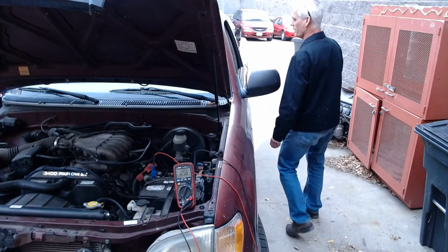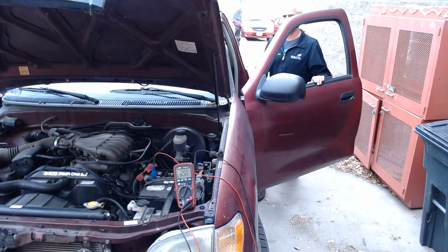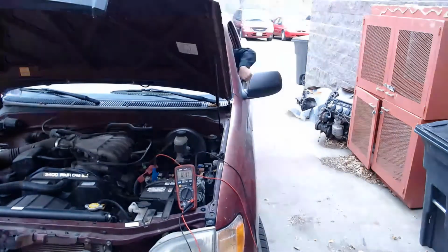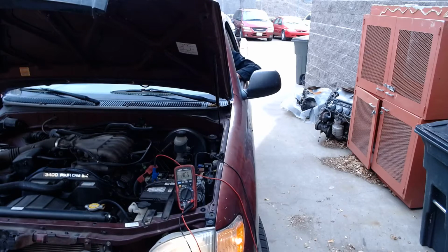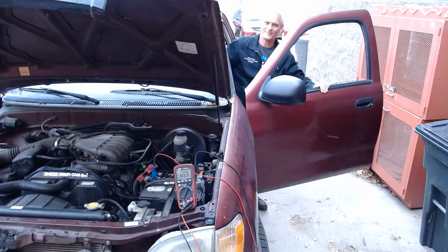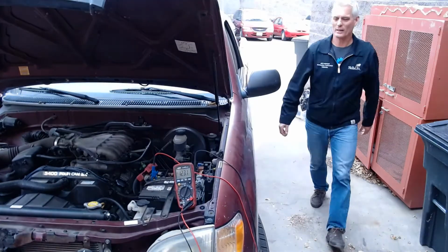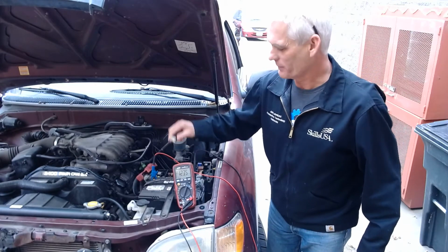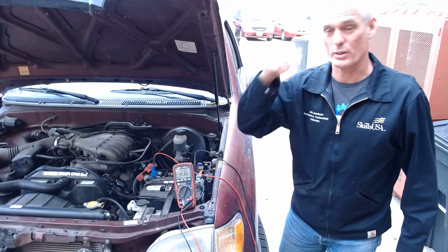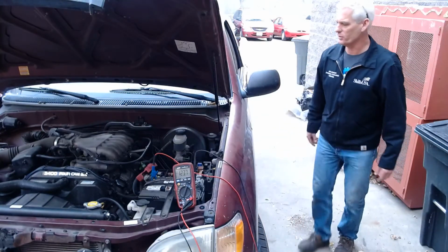Let's go ahead and try and crank it. Let's see what the voltage goes to. Now, of course, it's cranking. So whatever problem we had in the contact on the starter, it's got this self-healing feature. So I'm going to pull that circuit opening relay out, and I expect it to crank but not start. Let's see what the voltage goes to.